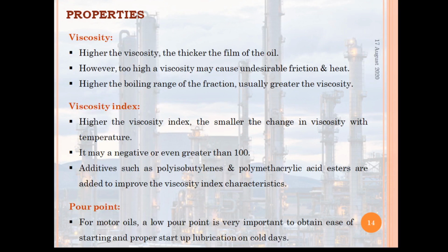Next, we elaborate these properties. The first one is the viscosity. As we know, the higher the viscosity, the thicker the film of the oil. However, too high a viscosity may cause undesirable friction and heat. The higher the boiling range of the fractions, usually the greater the viscosity.